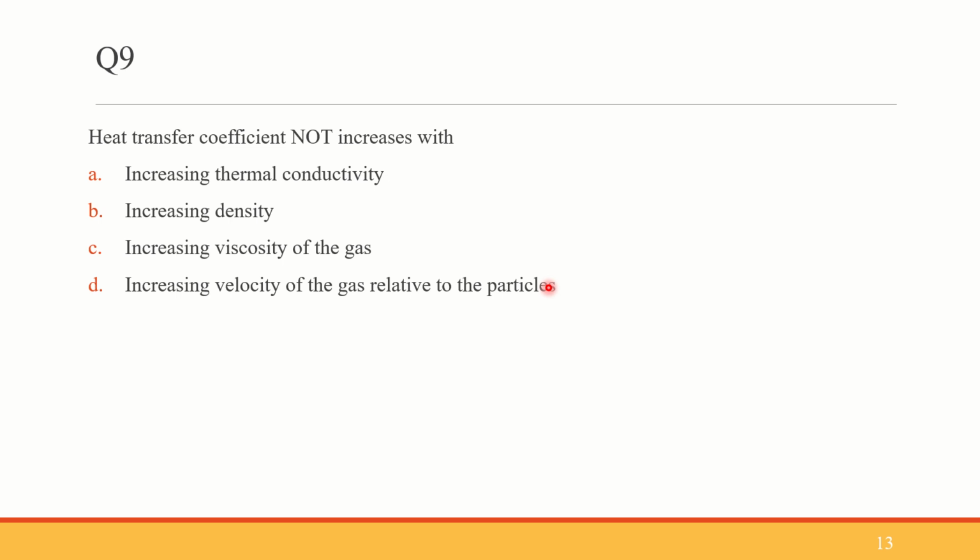To have a clearer understanding, we look at it clearly. What is given? Heat transfer coefficient does not increase with. So we'll see where it increases. It increases with increasing thermal conductivity, increasing density, decreasing viscosity of the gas, and increasing velocity of the gas relative to the particles.